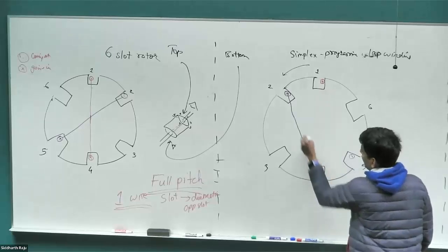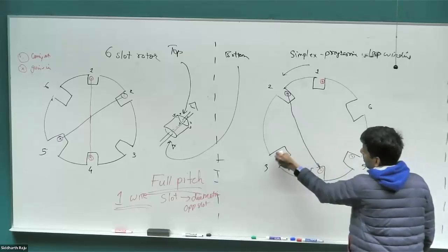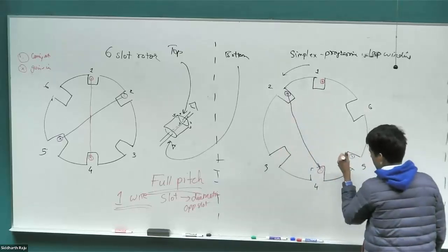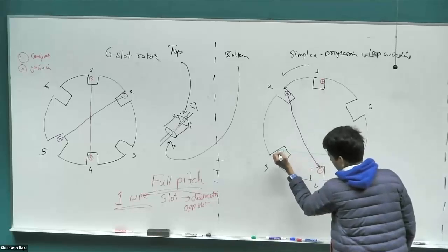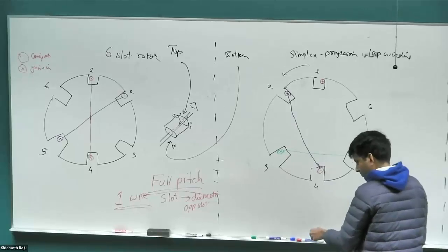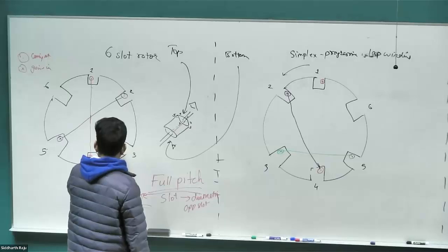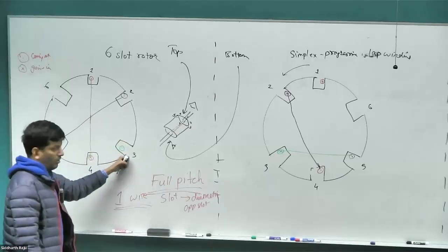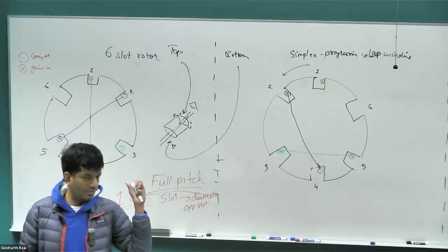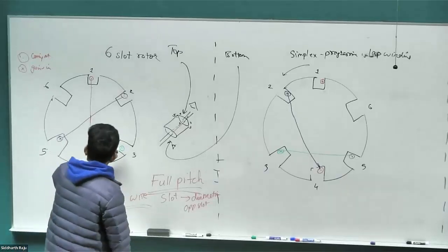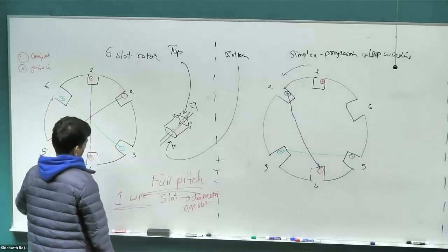Same as this, right? From 1 to 4, and then 4 went to one slot after 1. Now we are at 5, go one slot after 2. So we are going to go to slot number 3. So it's going into slot number 3. And then on the top view, of course, it's going to come out of slot number 3. On the top view, it goes from slot number 3 to 6, perfect. So it's always 180 degrees opposite on the top, again, for full pitch.